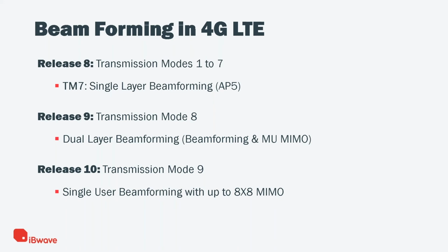Actually, in 4G, there are some basic concept of beamforming that was already defined in 4G. So let's go briefly through this type of beamforming aspect in 4G. It is known that MIMO is a fundamental component in 4G, and there are different MIMO operation mode defined for 4G. These MIMO operation mode are known in the standard as the transmission modes. In release 8, there were almost 7 transmission modes defined for 4G LTE standard.